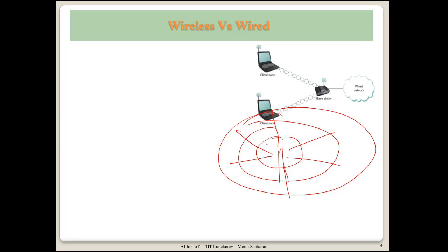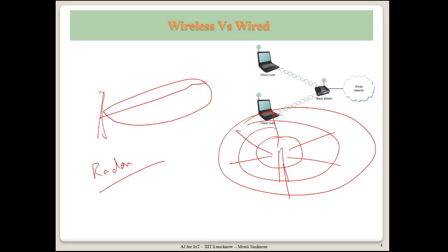They are not directional antenna, but some directional antennas send beams like this. Radars fall under this category. They send in a particular direction, the gain is more. This is called directional antenna. Whereas the gain will be coming down in other directions, and then there will be side lobes, wherein small leakage of signals may be there, but the majority of signal is directed in one direction.